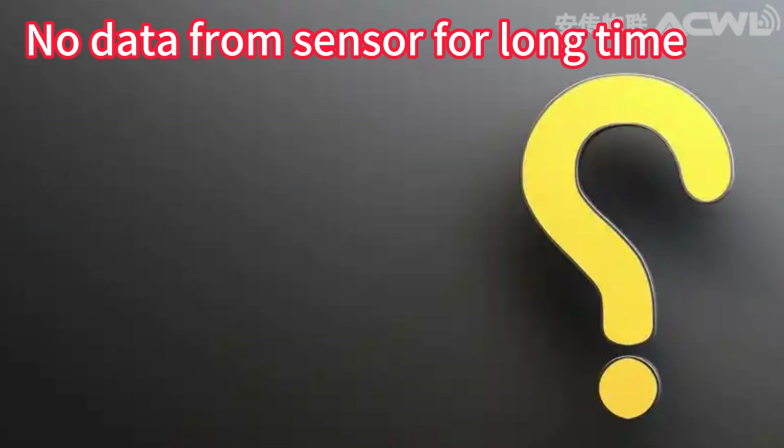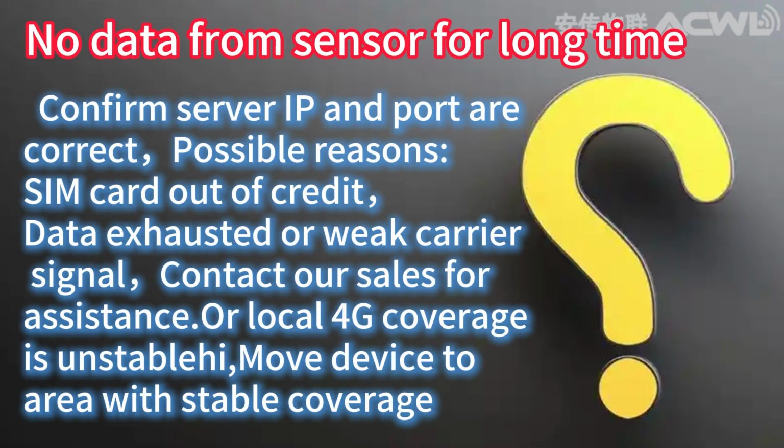Clean the probe, or replace the cable or probe if necessary. No data from the sensor for a long time: confirm the server IP and port are correct. Possible reasons: SIM card out of credit, data exhausted, or weak carrier signal. Contact our sales for assistance or check local 4G coverage. If it is unstable, move the device to an area with stable coverage.